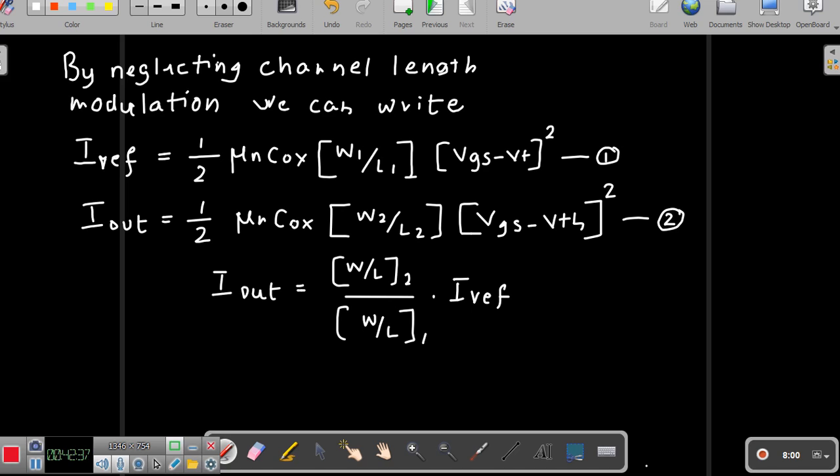The output current is constant regardless of the output conditions, regardless of the load condition. Basically it is a circuit designed to copy the current through one active device to control the current in the other active device, keeping the output current constant regardless of the loading condition.